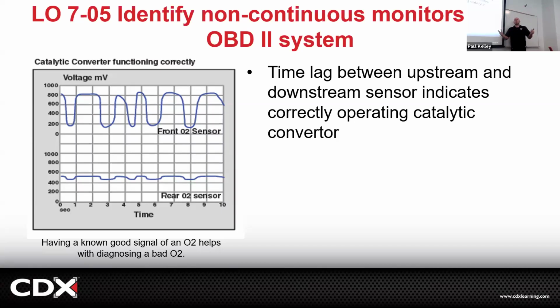So let's just say, hey, you're too rich. What do you think the ECM is going to do to fix that? If it's too rich, rich means too much fuel, not enough air. It's going to send a signal to the injector to spray less. Bingo. That's a major function of the PCM, right? It got information from the sensor: hey, you are rich. As a result, it takes that information, looks at its programming, which was written by the engineer in the tune, and it says, oh yeah, back the injectors off. Don't leave them open so long. Decrease the injector on time.